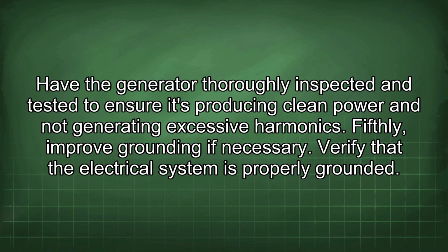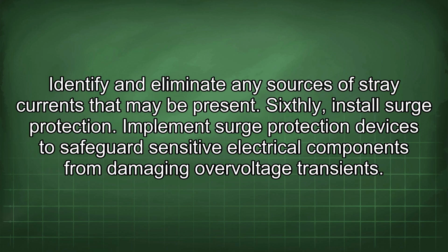Verify that the electrical system is properly grounded. Identify and eliminate any sources of stray currents that may be present. Sixthly, install surge protection. Implement surge protection devices to safeguard sensitive electrical components from damaging overvoltage transients.